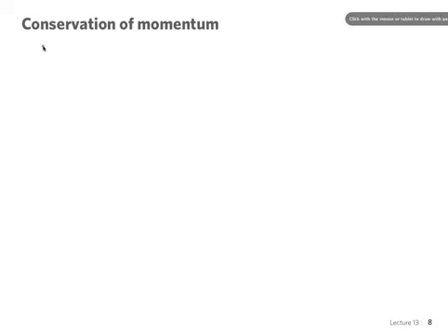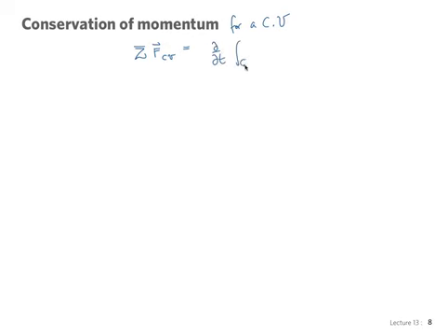So let's recall that we had our equation of conservation of momentum for a control volume. I hope you remember it. The most general one, before we simplified to 1D, steady flow, and so on, was this integral equation: the sum of forces in the control volume equals the partial derivative with respect to time, in the control volume, of velocity times rho dV, with this V being volume.